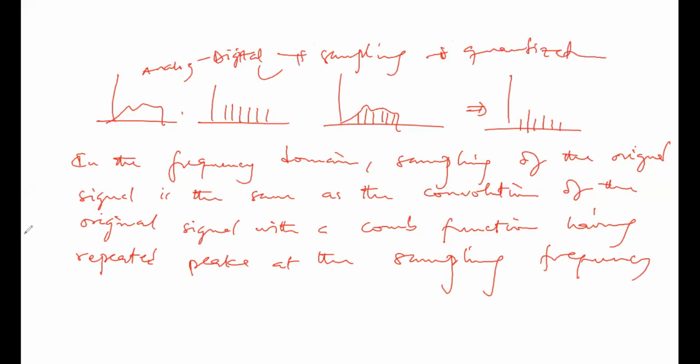So hence, the signals are quantized by mapping continuous finite values to a smaller set of discrete values so that an analog signal is digitized, okay? At this point, it should be noted that the sampling theorem specifies the minimum sampling rate at which a continuous time signal needs to be uniformly sampled so that the original signal can be completely recovered or reconstructed by the samples alone. This is more formally represented as the Shannon sampling theorem, okay?